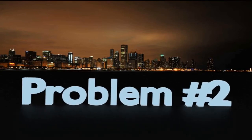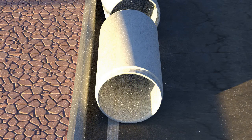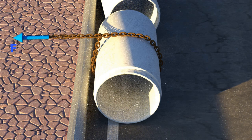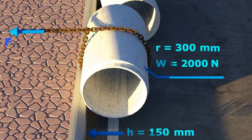Let's solve the same example with a little change in the question. Instead of direct pulling of the pipe, a chain is wound around the circumference of the pipe and F is applied in horizontal direction. If all other data is the same, find out the magnitude of R and F when the pipe is just lifted to move over the curb. Here also the pipe is just lifted and held in that position. It has not started moving.